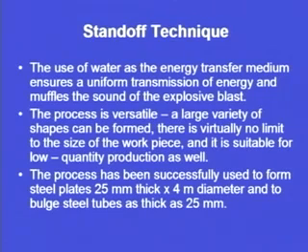So, the three basic advantages that we have seen in case of the standoff technique are that it can be used for a large variety of shapes, size is no limitation, and it is suitable for low quantity production. So, volume, size and shape in case of the standoff technique of explosive forming are no limitations. The process is versatile, a large variety of shapes can be formed, there is virtually no limit to the size of the workpiece, and it is suitable for low quantity production as well. So, this is a brief summarization that we have discussed.